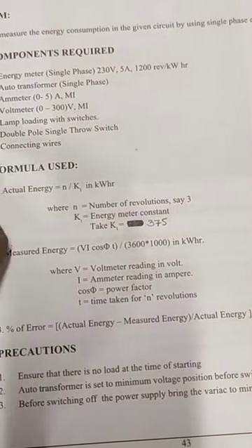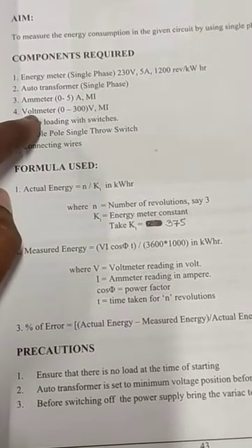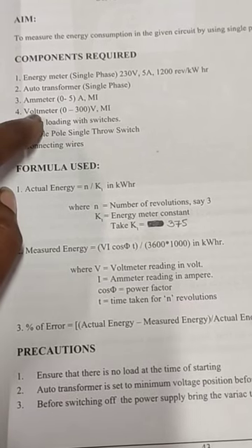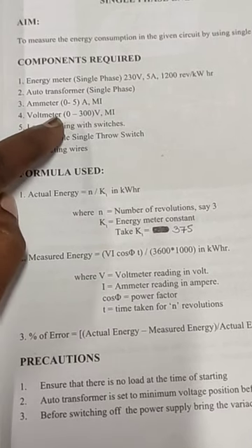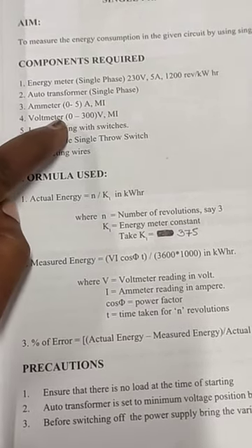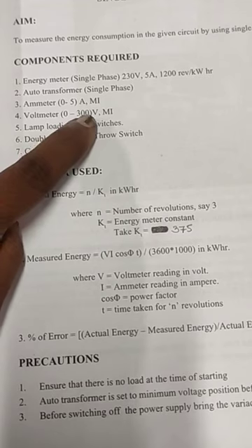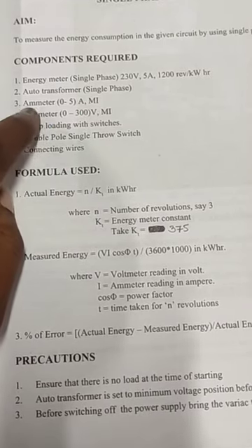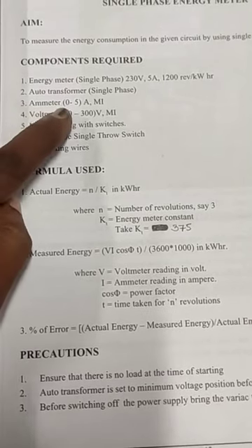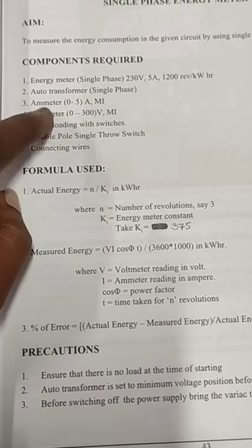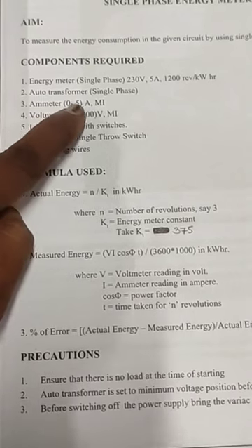The major components for this are an ammeter as well as a voltmeter. Since we are dealing with AC voltage, we have a rated voltage of 230. In an instrument, we have multiples of 75 or multiples of 150. We don't have exactly a 230 volt measuring range, so we take a voltmeter with a range of 0 to 300 volts. In the same way, in all residences, when you are working with a simple load, it must have a minimum of 5 ampere capacity. So we are taking an ammeter with that minimum range only, varying from 0 to 5 ampere.